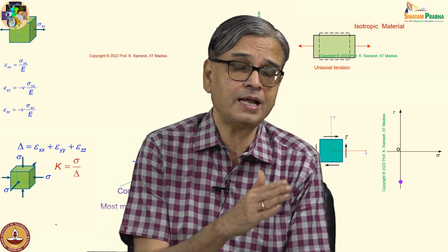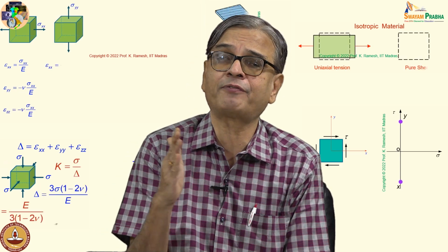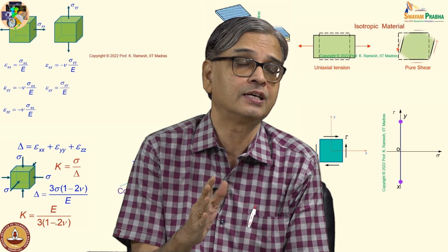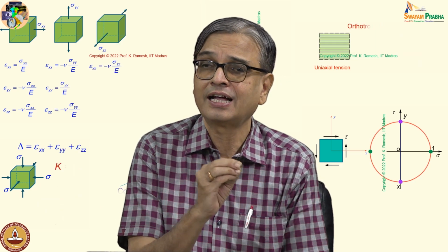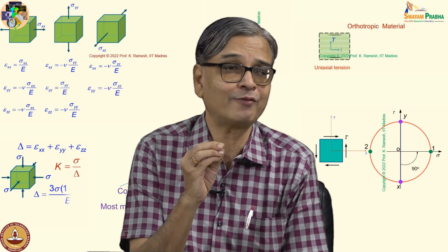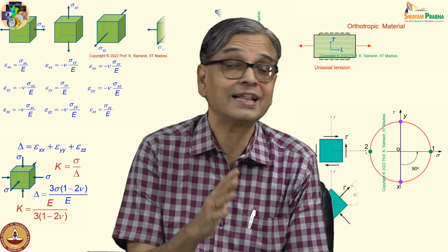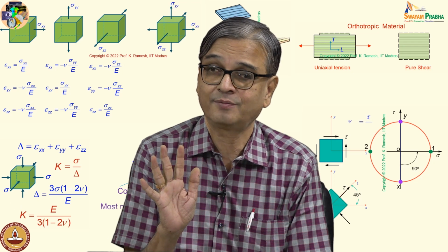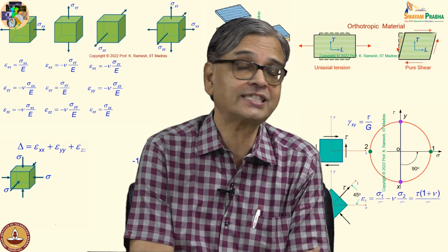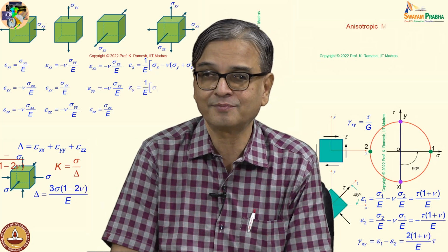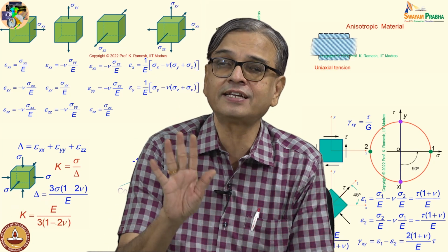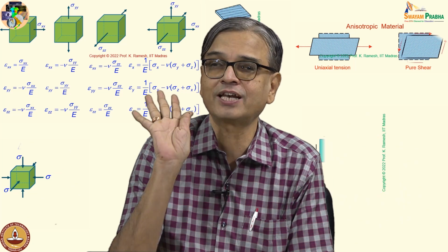See, when people approach the same problem from different perspectives, if you agree on the essential analysis that you require only 2 elastic constants, that gets reinforced. Because I told you at the start of strength of materials, people started that you need only 1 elastic constant, because they assumed for all material Poisson ratio is a fixed value of 0.25.